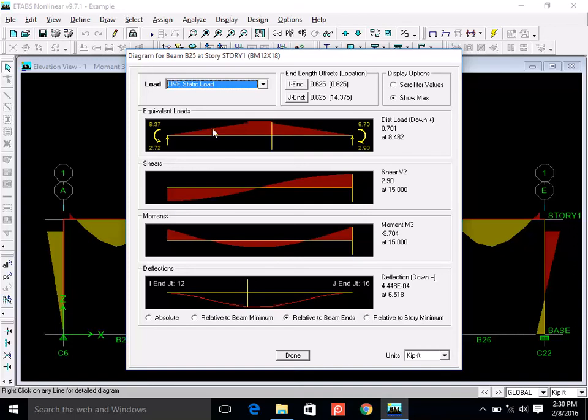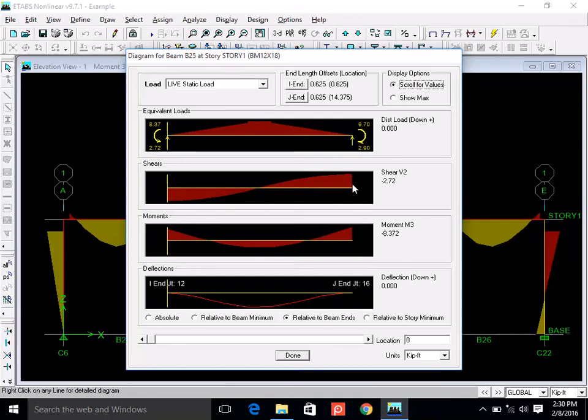Okay, on this panel you can see the load, the distributed load, and this is the shear force diagram. Oh, this is completely black on the screen. Do you see it on your screen? Yes, sir. But at least you can read the values. Actually, there is a shear force diagram, there is a bending moment diagram, and this is the deformed shape, which is not visible. But you see these values: 2.72 shear, 8.38 moment. Okay, and right here is the load diagram. And right now we are looking at values at this location. But you can move this anywhere. So along the length of the beam, right here, the shear is this much, moment is this much.